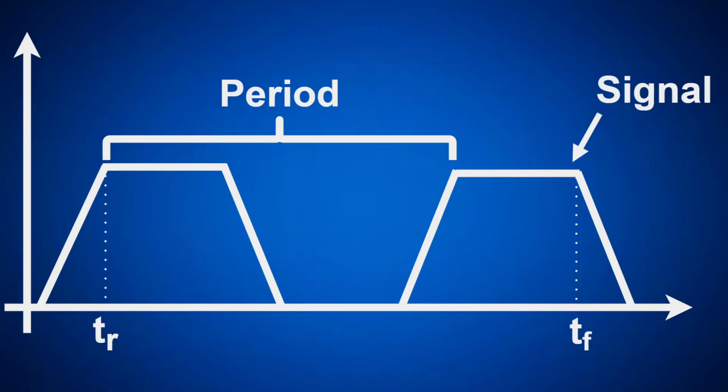But one thing I would caution you about sizing the resistors for EMI is that too long of a rise time can actually impact the functionality of your digital circuit. So that's something to be careful of. A general rule of thumb is that the periodic signal's rise and fall times should not account for more than about 1/10 of the signal's period. And also note that for power supply circuits, adjusting that gate resistor on the MOSFET will also impact the amount of power it dissipates and therefore its thermal performance. So those are just some areas that you want to look out for, but we'll talk about those in another video.